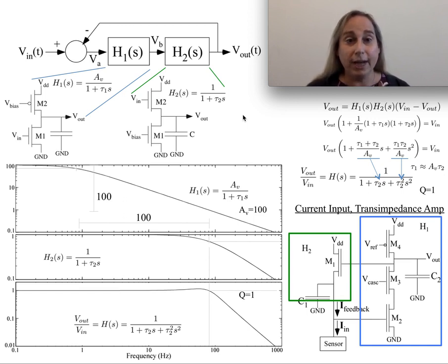And so if you were to say, well, how would I think about these kinds of structures? Well, you could think about one structure as being a high gain amplifier, but again, it has a first order pole because there's going to be some capacitance there. So you might imagine it being like a common source structure. You might get something that's like a source follower that also has a low gain, so a gain of say 1 or kappa. Some might look at this and go, wait, this gain should be kappa, and that would be correct, but we'll just keep it simple for the moment, and keep it at 1.